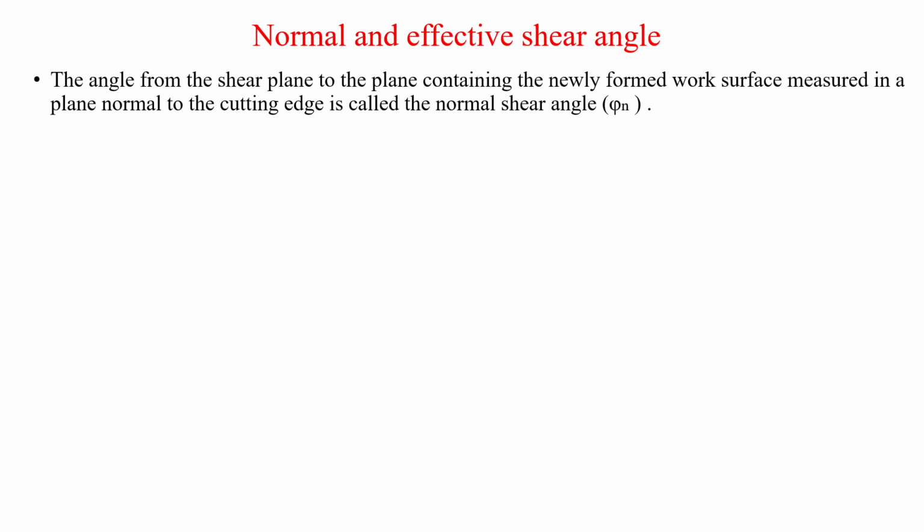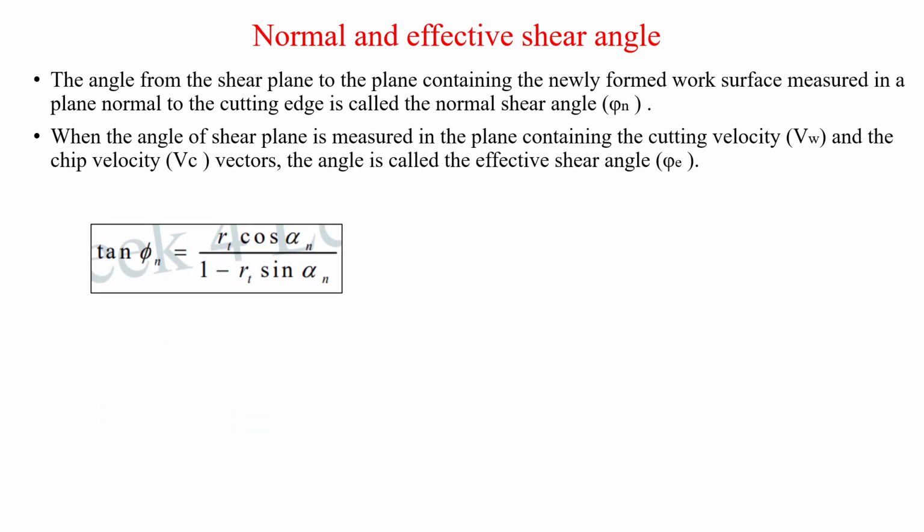Now, one is the normal shear angle. What is the normal shear angle? It's the angle from the shear plane to the plane which contains the newly formed work surface, in a plane which is normal to the cutting edge. I'll show you.